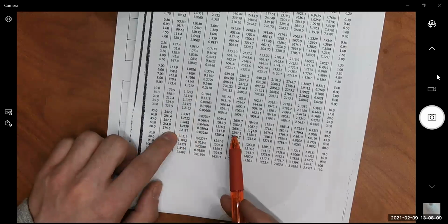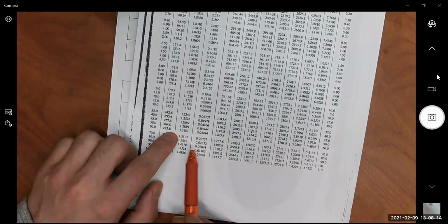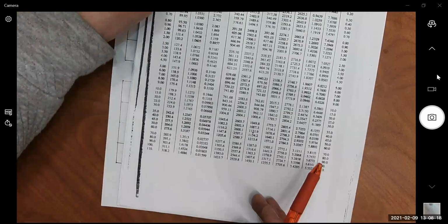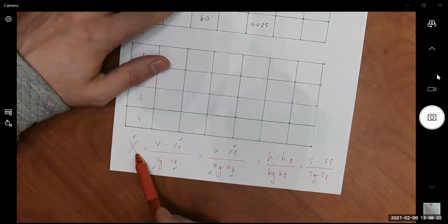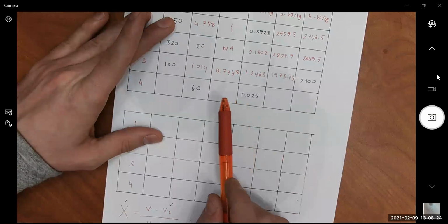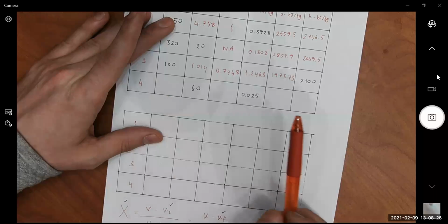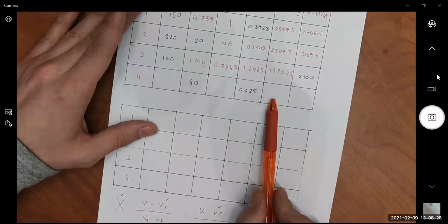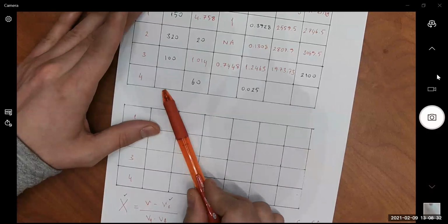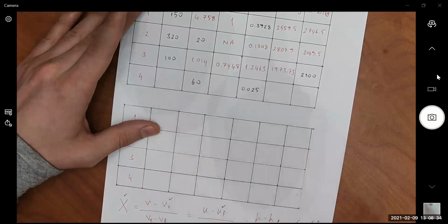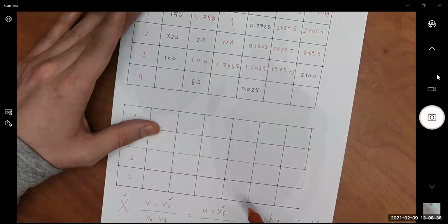All right. So in that case, you are in between again. Using the quality factor calculation to find your quality factor, temperature, internal energy, and enthalpy. You don't need to calculate your temperature. The temperature in this case is the saturation temperature since you are on the saturation curve.